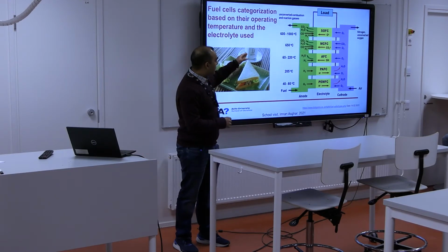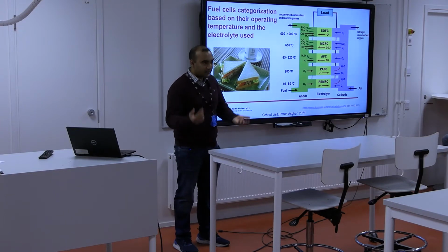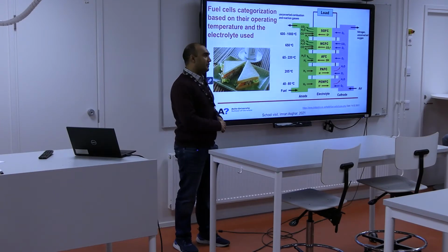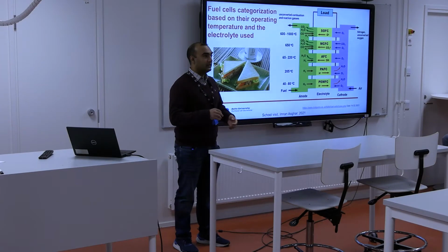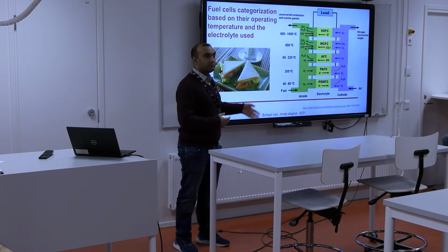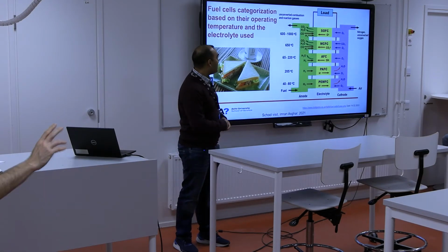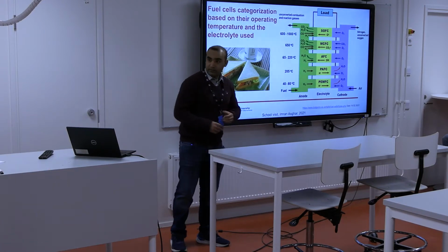But if you look at the operating temperature, they operate at very high temperatures, which has advantages and disadvantages. When they operate at very high temperature, degradation reactions can happen, and we have limited choice of materials because there are not many materials which can be stable at that high temperature. That's why ceramic materials are used for that purpose. But the good thing is, yeah, please.